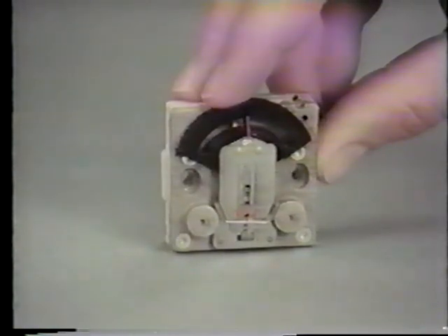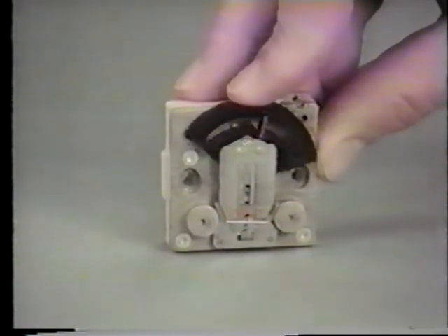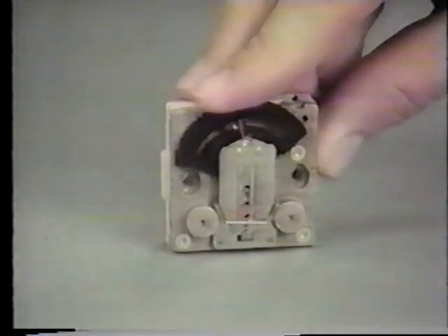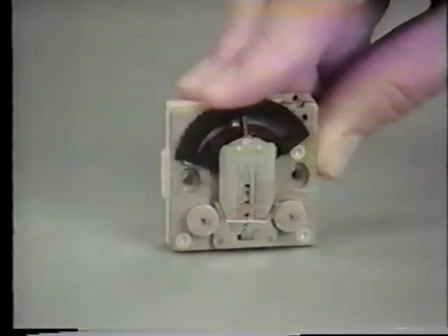The set point and throttling range adjustments are accomplished with the serrated thumb wheel on the top of the thermostat and the throttling range slide on the bimetal, like the other thermostats previously discussed. The reverse action of the thermostat is calibrated by the reverse acting calibration screw located in the center of the bimetal. The direct action of the thermostat is calibrated by the screw here in the lower left of the thermostat.